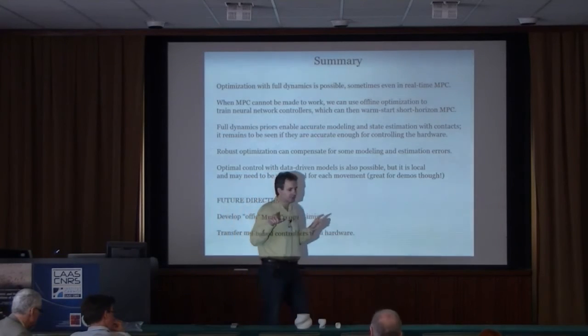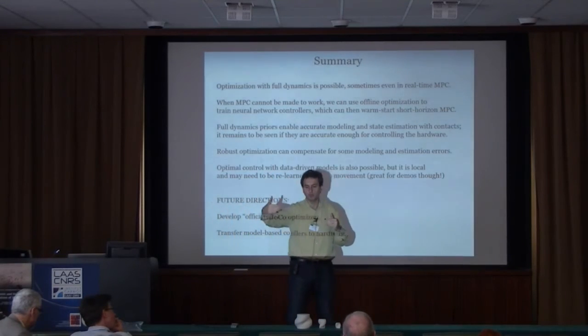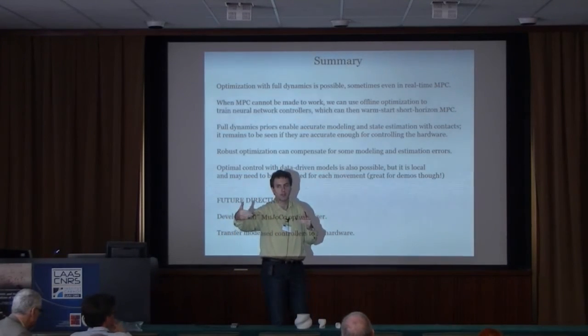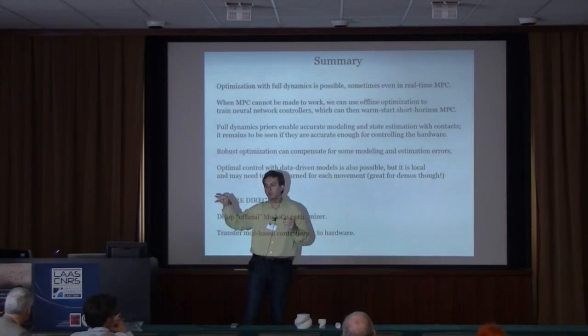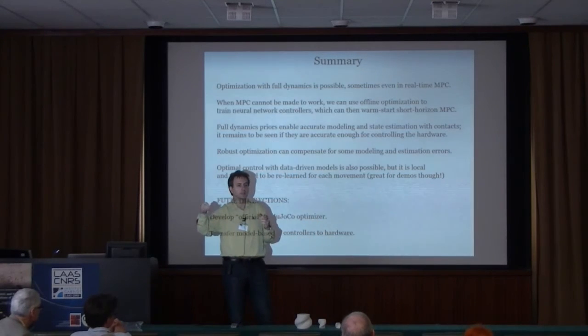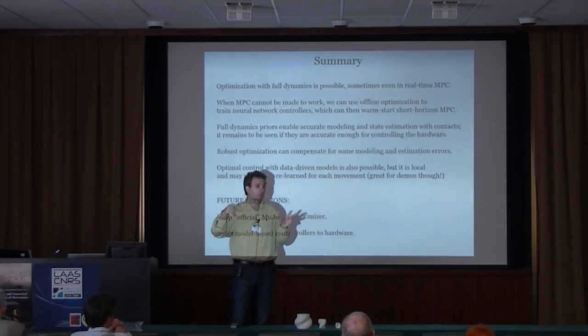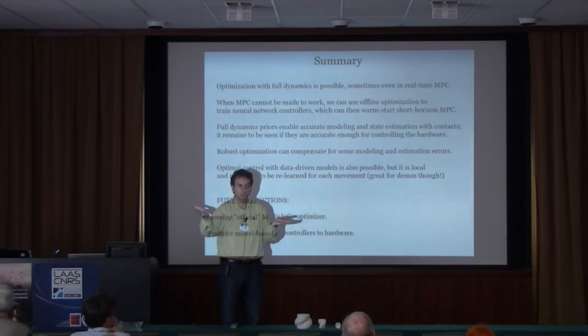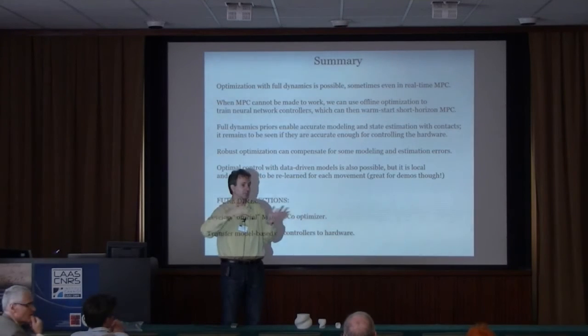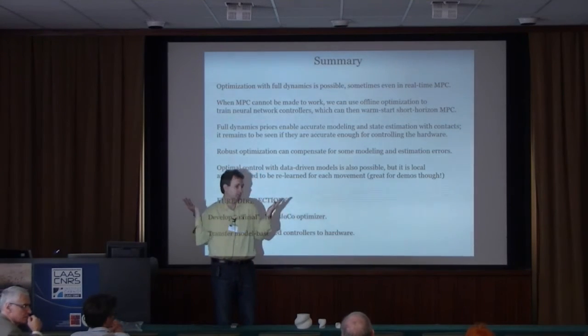So these are two different questions. Terminal constraint usually means what do you do at the end of the horizon when you cannot look anymore. Ideally, you would have some approximation to the optimal value function, where the optimal value function basically says how good is the future starting now. And if you had that, you should put it in. We don't, so we don't put it in. So our terminal cost is just the running cost and nothing else, because we don't know how to build those heuristics.